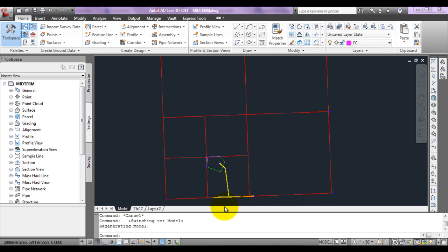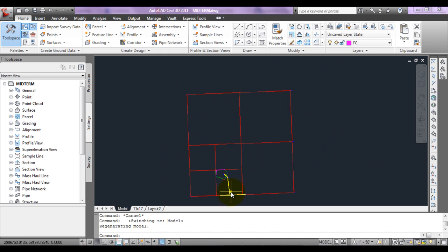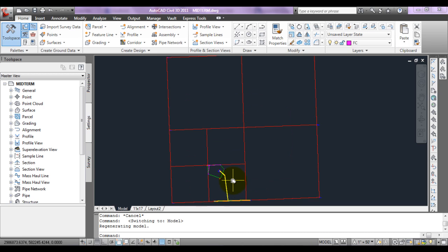And what I mean by controlling corners is there's a statute that says that our plat must show all controlling corners. And controlling corners mean which corners do you need to know, which section corners do you need to know in order to plot out this property or to find this property's corners. And because our property starts at this corner, there are many corners that are needed. We had to subdivide the section to get that corner.